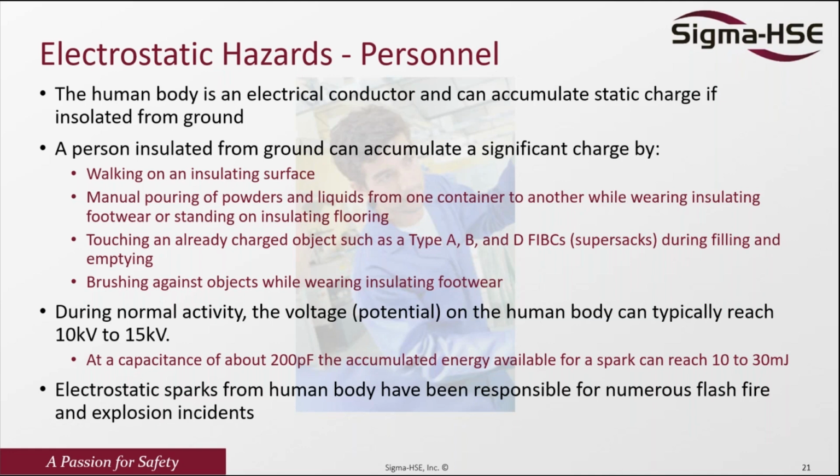And sometimes rubbing against an object, as I said, in case you have a balloon, you rub it, you can see that it will automatically charge. Or maybe in case you have a plastic container, you rub it, you can see that this material will actually automatically charge. During normal activity, the voltage on the human body can typically go up to 10 to 15 kilovolt, and with as little as a 200 picofarad capacitor, the energy can reach maybe 10 to 30 millijoules, which can actually ignite dust, gas, and solvent. And this has actually caused several fire and explosion incidents in the industry.